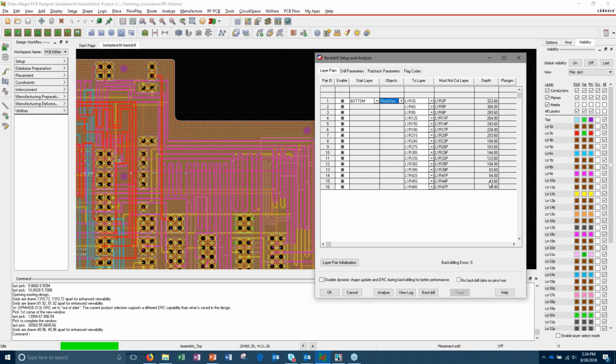Again, the important thing is making sure your stack up is correct. We want your stack up to be correct. This is what it's basically running off of, that stack up, and then it creates those files for you automatically. That's part of the benefit. If I was doing this in my standard workflow, I would be doing all this stuff and calculating it myself, and doing fab notes to cover everything that I was trying to do.